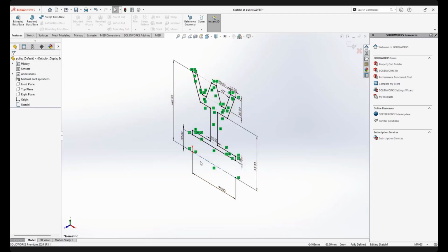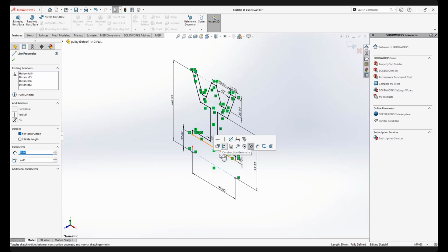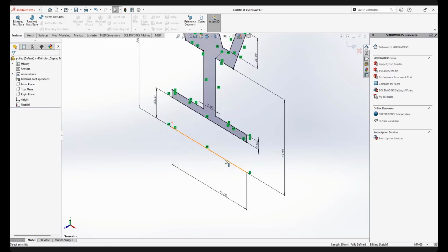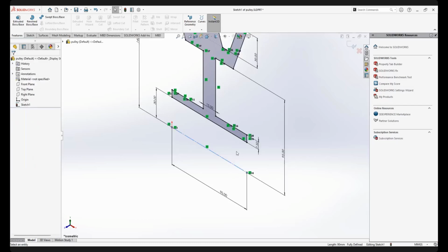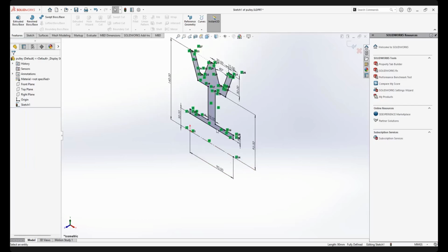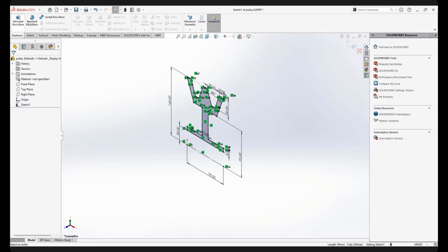Guys, sometimes you accidentally, sir, why you draw it solid line? You can see this one. You make it solid line. No, do it center. Okay, if you do it solid line, you can change it. You select the line. There's an icon here. You make it as this, the second icon. Construction geometry, you become center line. All right. Okay, you go features and you go to revolve.